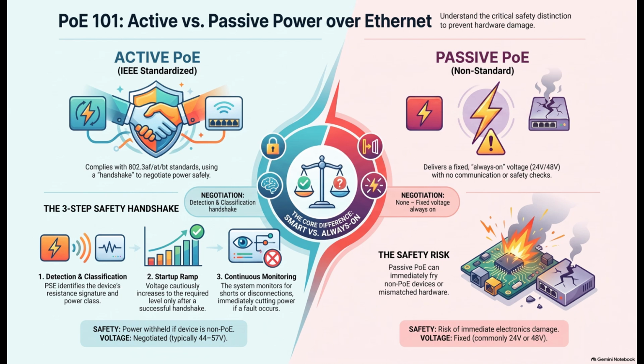You really do. You go from the train track metaphor straight into detailing how PoE is a Class 2 circuit delivering 44 to 57 volts DC and requiring a specific resistance between 23.75 kiloohms and 26.25 kiloohms during the discovery phase.